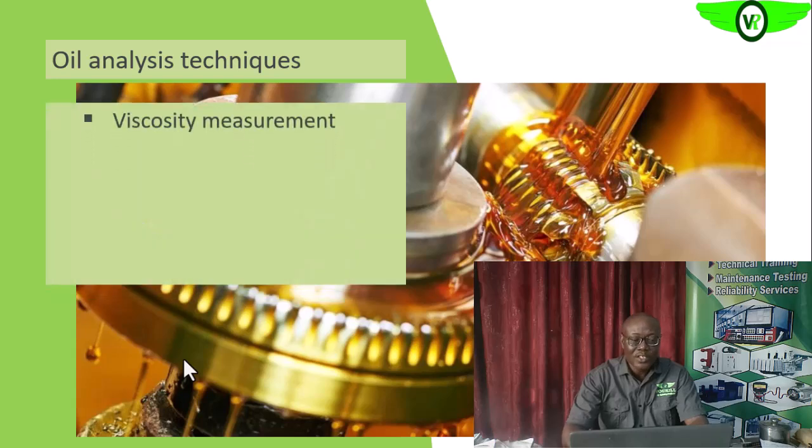The first is viscosity measurement. You take a sample of the oil from the equipment and test for the viscosity. Of course, as the viscosity is going down, we know that the lubricating capacity of the oil is also reducing, which means the mating parts that you expect the lube oil to lubricate will have less lubricant.